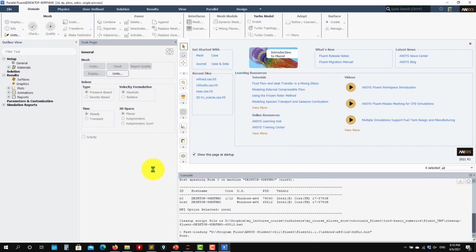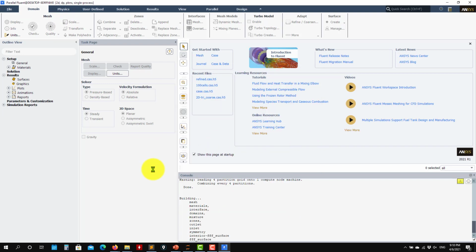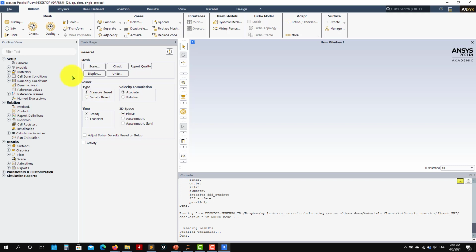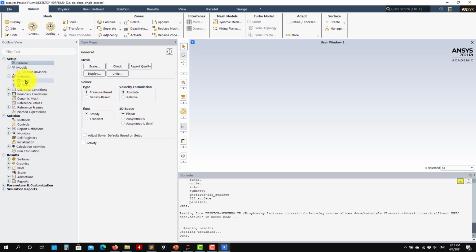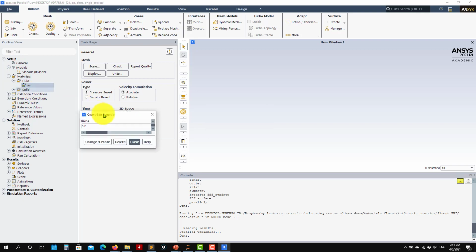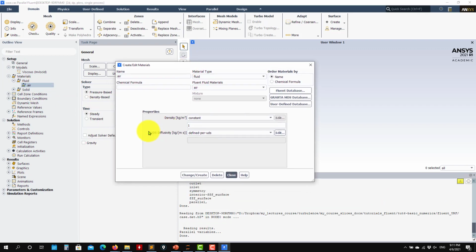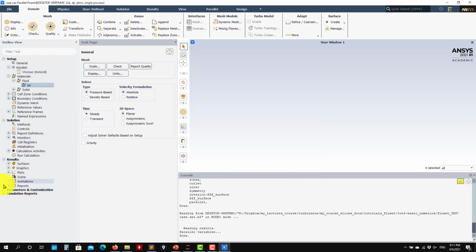Okay, I'm reading the case. And we have everything. So here you have the case setup. So let me go through the case setup. See that steady models is in basic physical properties. As you enter here, you see the diffusivity coefficient for the scalar equation. You put it to 0. And remember that you define the passive scalar or the general transport equation here. User defined scalar, and we are defining one equation, okay?